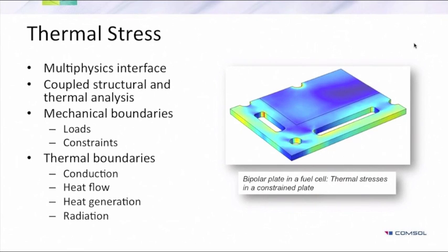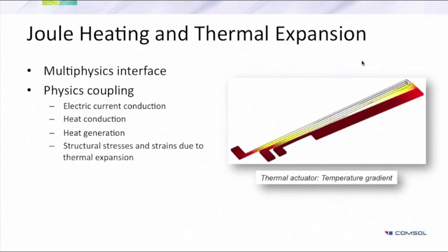For those cases when you need to interact with different physics, COMSOL also has predefined interfaces. For example, the thermal stress interface couples the structural behavior with the thermal behavior, so that we can prescribe both mechanical loads and thermal boundaries. Joule heating and thermal expansion is another example.